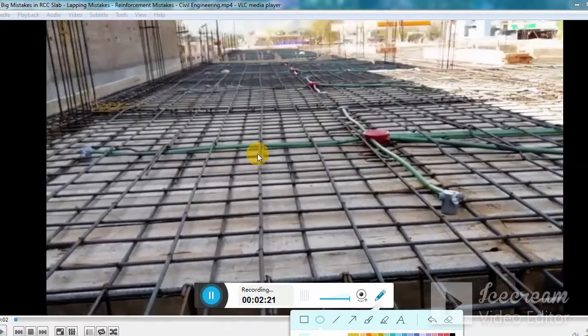you never allow such kind of conduits in your structural system. Why? Because it creates a very weak section. For example, you see this pipe which is just over here. Sometimes they use larger size pipes. Clear? So the thickness of the slab, if you do slab designing, for example, we use a specific thickness of the slab. Clear? That is around about 6 inches.